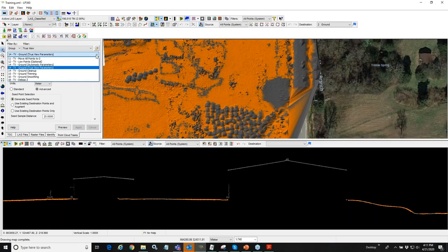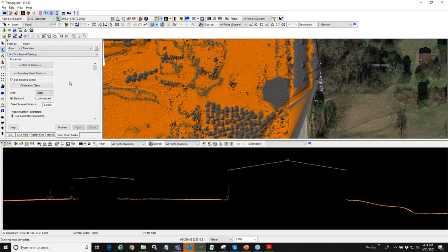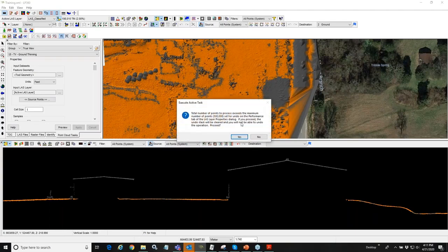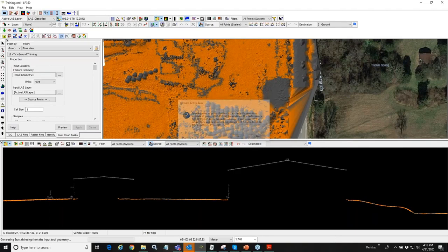But we have a nice tool that you can use if you see something like that. We just call it a cleanup tool. Again, it's a point cloud task, so I could configure these things as I saw fit or wanted to do. In this case, of course, I'm not going to run it against the whole project area. I'll probably just take, that's a little bit big. I'm just going to use a stamp here.